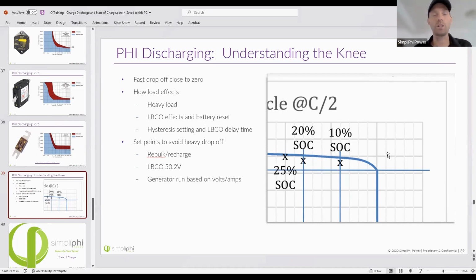And even if you continuously do that, if you are having equipment that drops your battery below 48 volts, it can even void your warranty. So pay attention to these settings, your low battery cutout on your inverter. I recommend that you set your low battery cutout for a daily cycled battery to a 20% depth of discharge, which will be around 49.5 volts. And 10% state of charge or 100% state of charge if you're really only using it for battery backup.